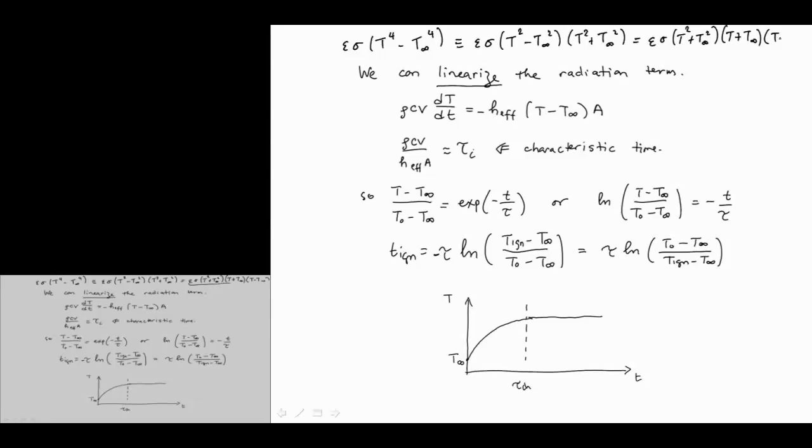So all this stuff, sometimes people think about as a radiative heat transfer coefficient. It clearly depends on the temperature, so it's a nonlinear dependence. As a construct, we understand that there is a linearization that's possible, and we might think about having an effective heat transfer coefficient, which is nothing more than the convective plus the radiative component. And